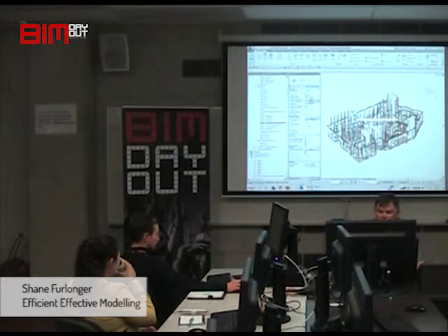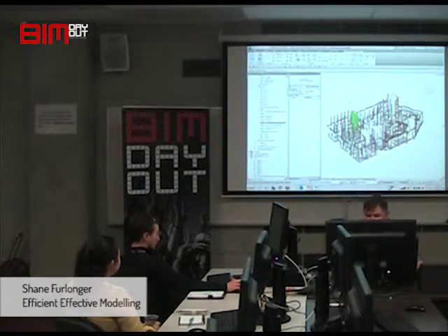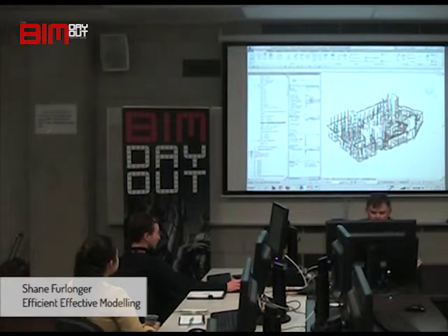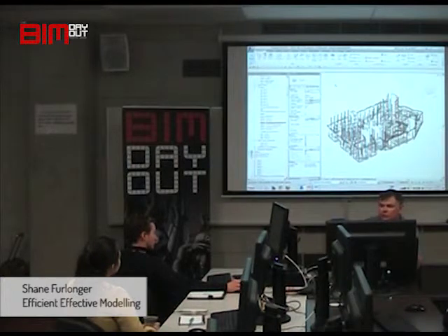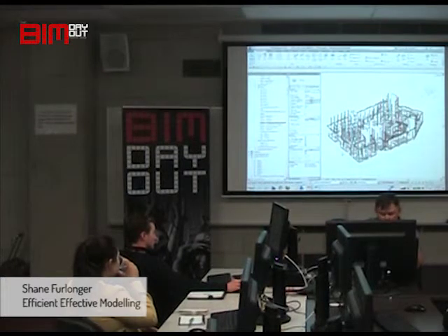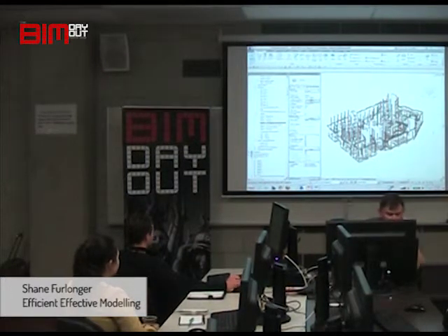It also means you can check certain things out, like that's the core. I've got this set up as a structural wall, because that's what it was, and if I had brickwork showing up in here, which in this model wasn't structural, I'd know I've got something set on the wrong setting, because this view only shows structure. So it allows you to do a bit of a cross-check on your model and see what's happening in various places, if you've got everything on the right work set, or how you've got the model set up.